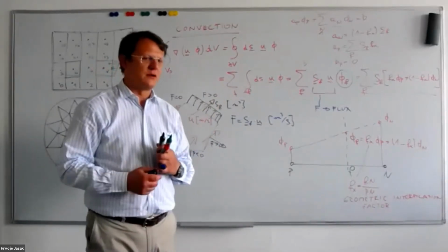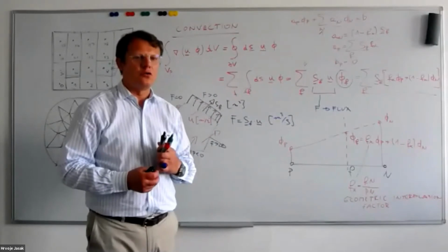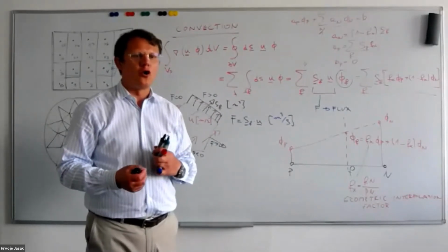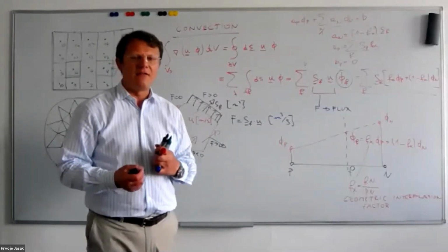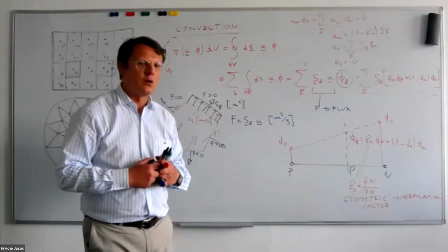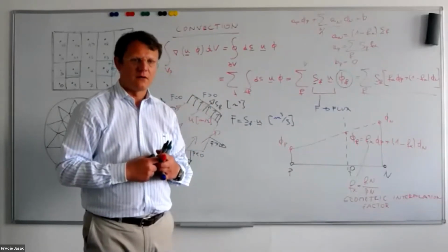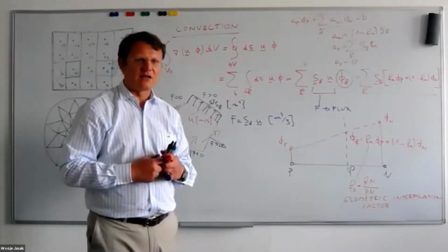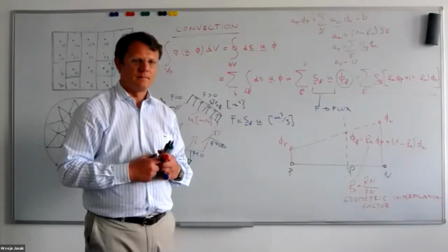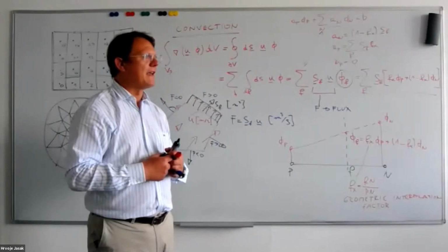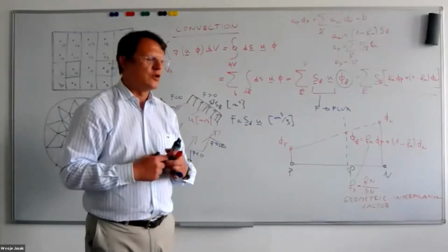And in order to preserve boundedness, we need to use other schemes like upwind differencing or nonlinear TVD or NVD family schemes, which will account for the direction of transportedness. Please have a look at the slides for more details. In the meantime, let us press on with our final term in the equation, which is the diffusion term.